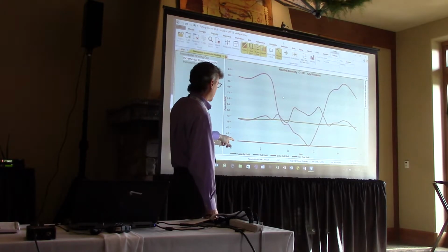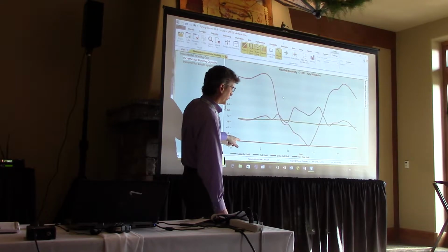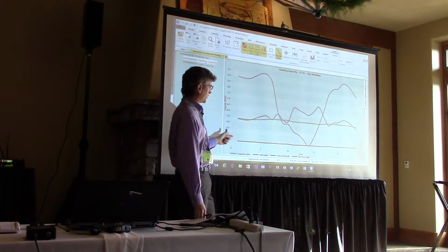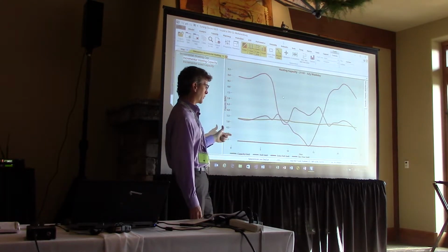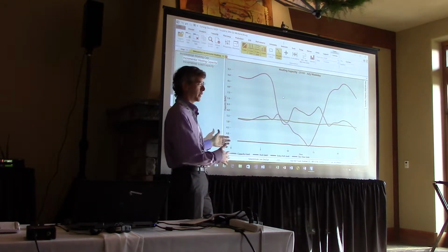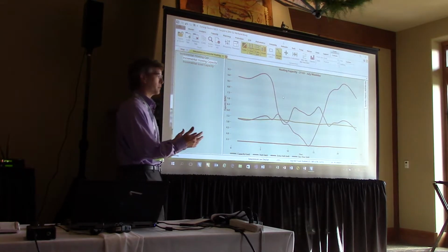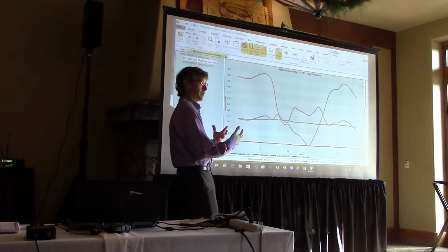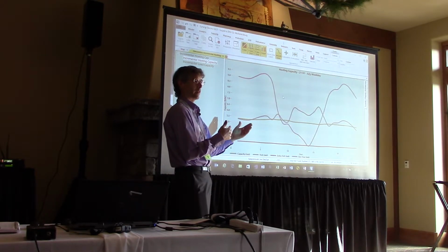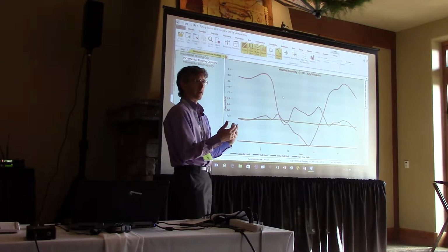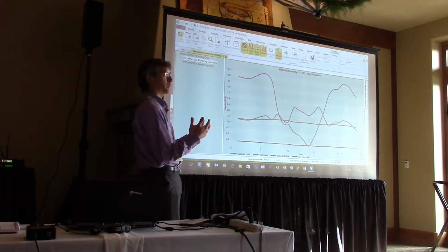And so now we've got the delta voltage limit here, which is in the model settings. I've got mine set to 3 volts. And this is a difference in the way we're looking at delta voltage versus some other stuff out of the industry that you may see. And I'm not sure, but I think they're looking at delta voltage as more of a longer term after the tap changers have had a chance to operate. I could be wrong, and there's nothing wrong with that.